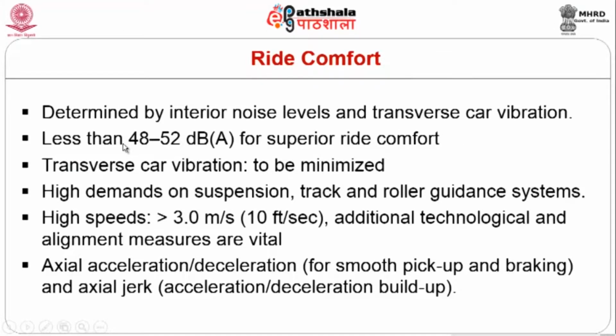We need to ensure that the noise levels are 48 to 52 decibels for superior ride comfort. Transverse car vibration has to be minimized to the maximum extent. High demand on suspension, track and roller guidance systems helps a great deal in taking care of the vibration.